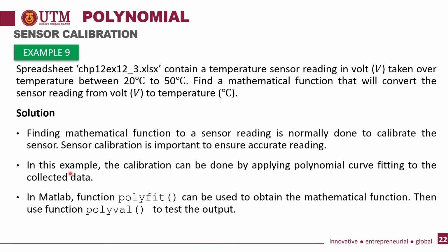In this example, the calibration can be done by applying polynomial curve fitting to the collected data. In MATLAB, the function polyfit is used to obtain the mathematical function from the data, and then we use polyval to test the output of the equation that we get. So is it accurate or not?